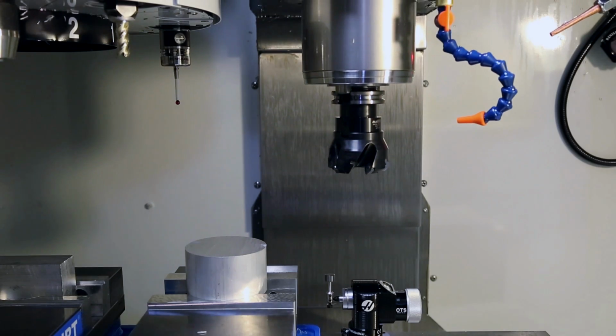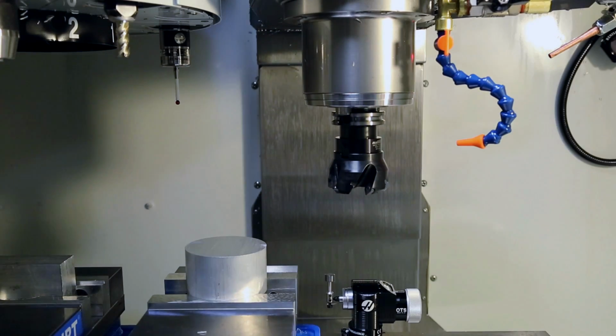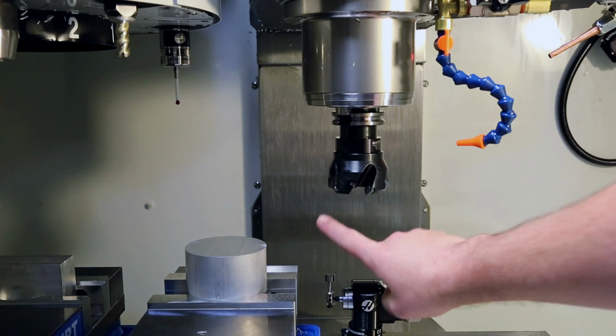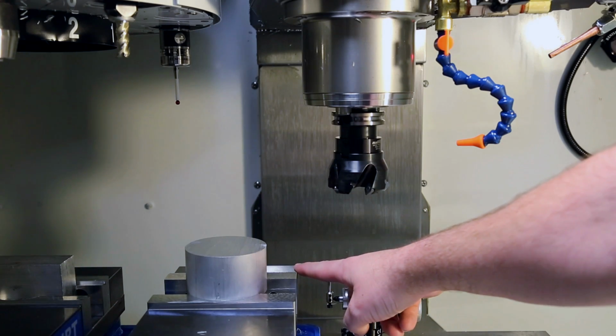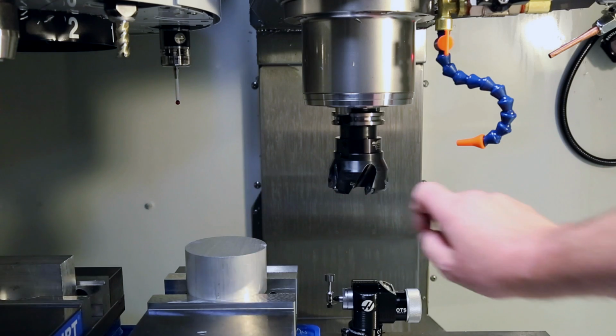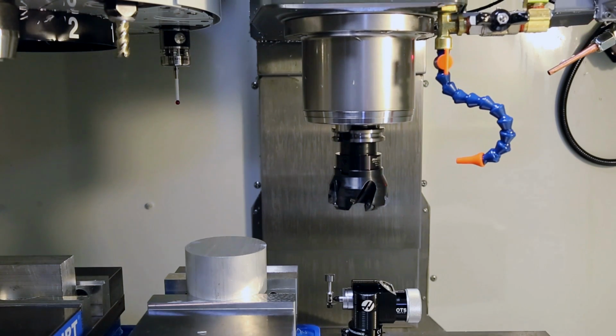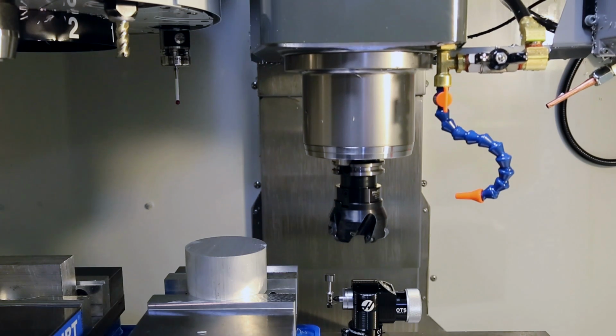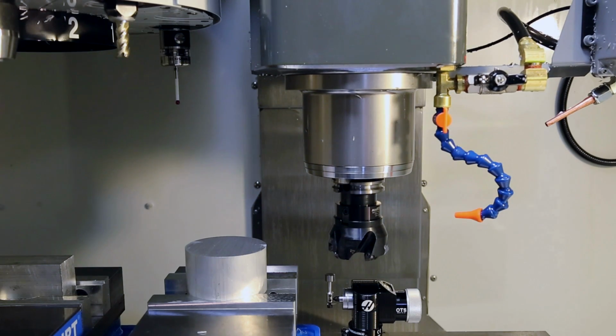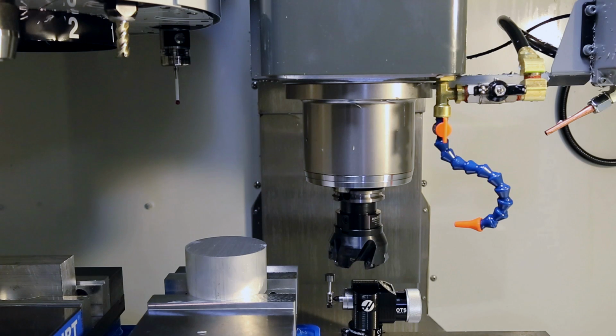Before running the routine, we must manually handle jog the machine into position. Use caution to avoid vices and work holding fixtures when jogging the Z-axis downward with the large face mill tool. Furthermore, slow the jog rate and use caution while approaching the tool setter. At no point should the tool ever contact the setter while jogging.